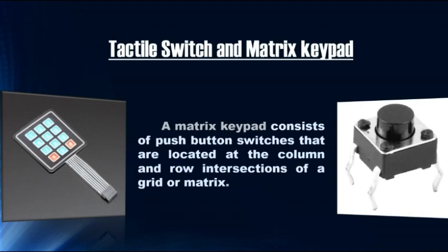We encountered an important concept in the second phase of our internship, the debouncing effect in switches. When a switch is pressed or released, it can produce rapid electrical fluctuations, causing multiple unintended readings. We learned some of the methods to implement debouncing effectively, ensuring the reliability and accuracy of the user inputs in our microwave oven project.